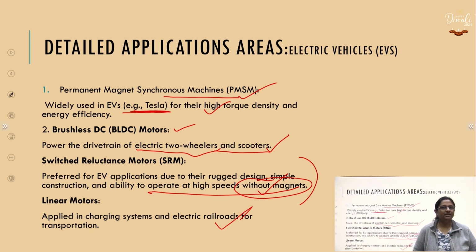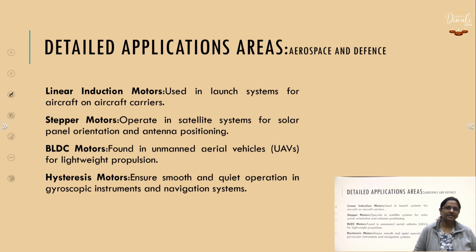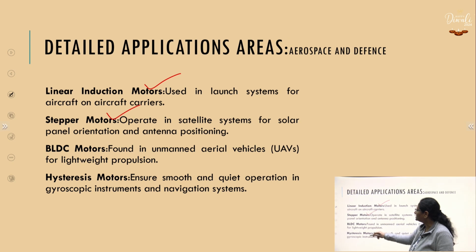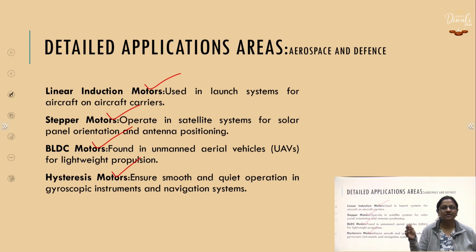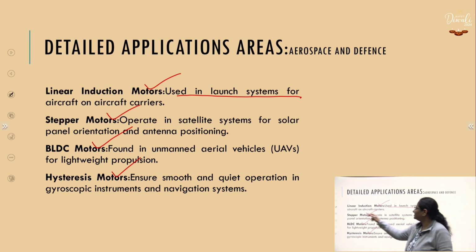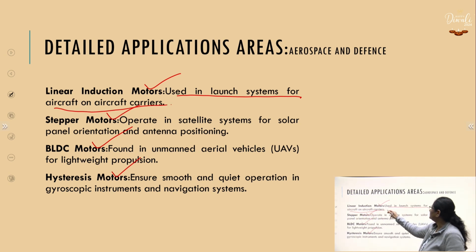The next detailed application area is aerospace and defense, and the various motors which are employed are linear induction motors, stepper motors, BLDC motors and hysteresis motors. The hysteresis motors are basically a special type of single phase synchronous motor. Which one is used in launch systems? The linear induction motor, for launch systems for aircraft on aircraft carriers.